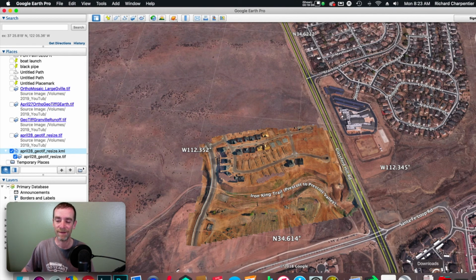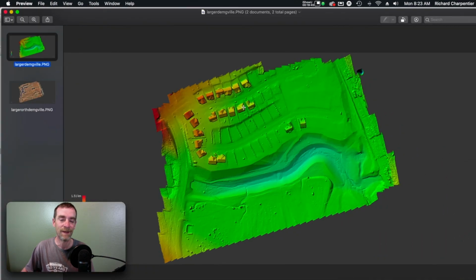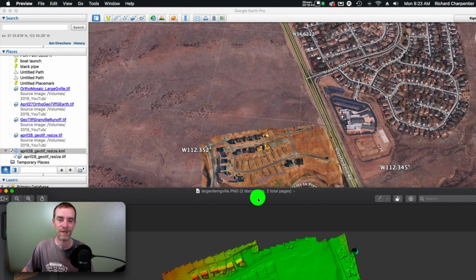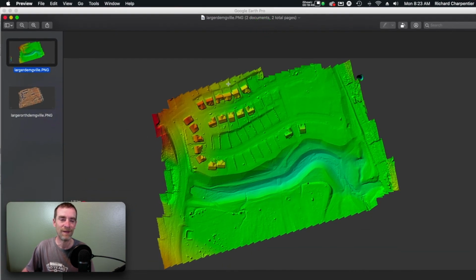And then finally, the last thing that was really exciting is getting to show off this digital elevation model that's associated with that model there. And it really gives you a feel. We've got high ground here, during monsoon season, we'll probably see runoff coming down here, and we can see the very lowest areas in here. So this is going to be a big wash, and that wash also goes underneath the highway on the right-hand side here.